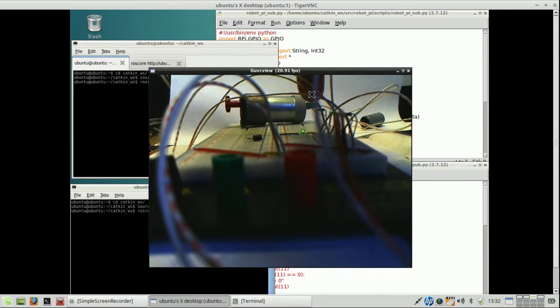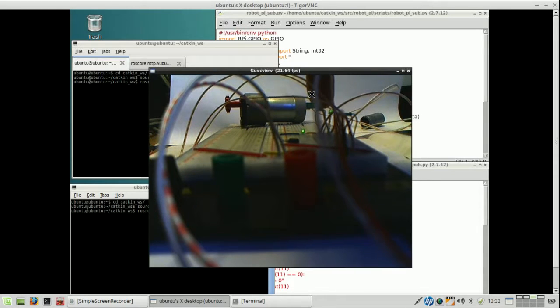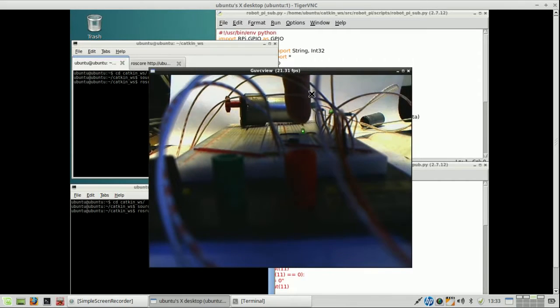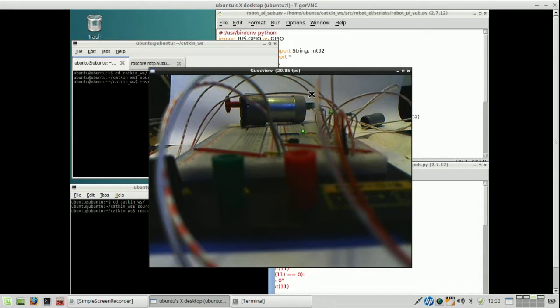The objective is to run it through this circuit with a transistor, a resistor and 2 LEDs, and that didn't work as intended when I put the transistor into the circuit. This LED and this LED do not work. Without the transistor obviously they do, but well, that's not the desired configuration.